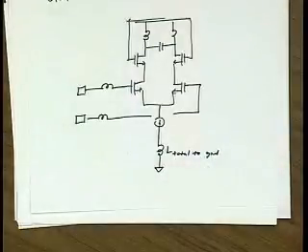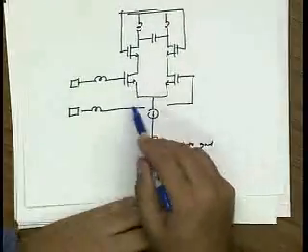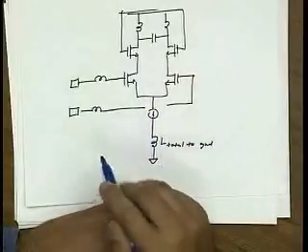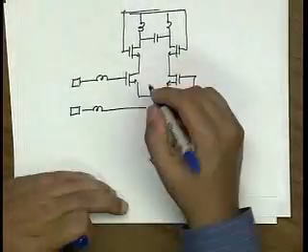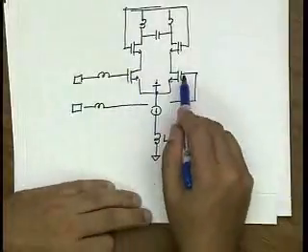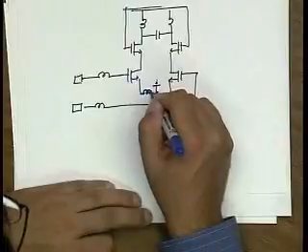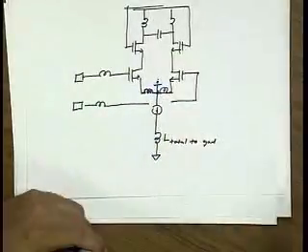Now the nice thing about a differential version of the LNA is the inductance on the source side here, on the coupled source side, doesn't matter because on chip this is a virtual ground. And if I want to degenerate these devices, I would actually just put physical inductors in the layout. So these would be on-chip inductors.